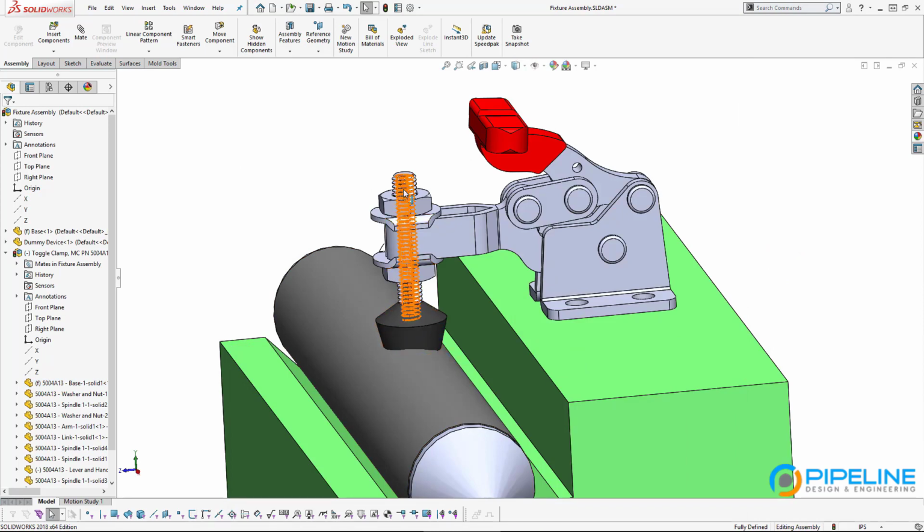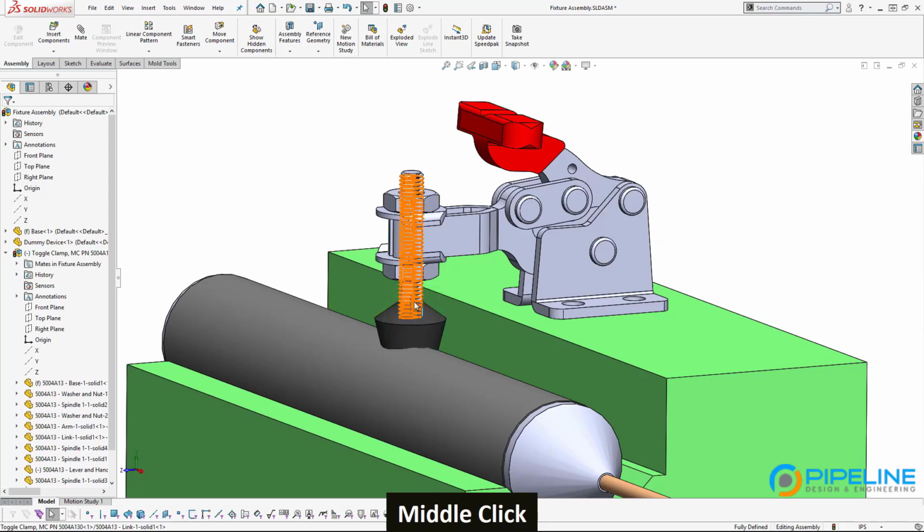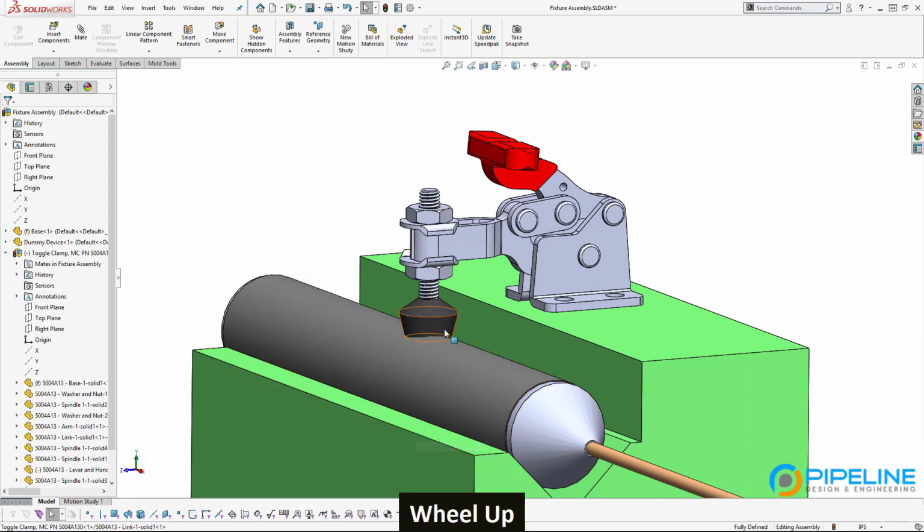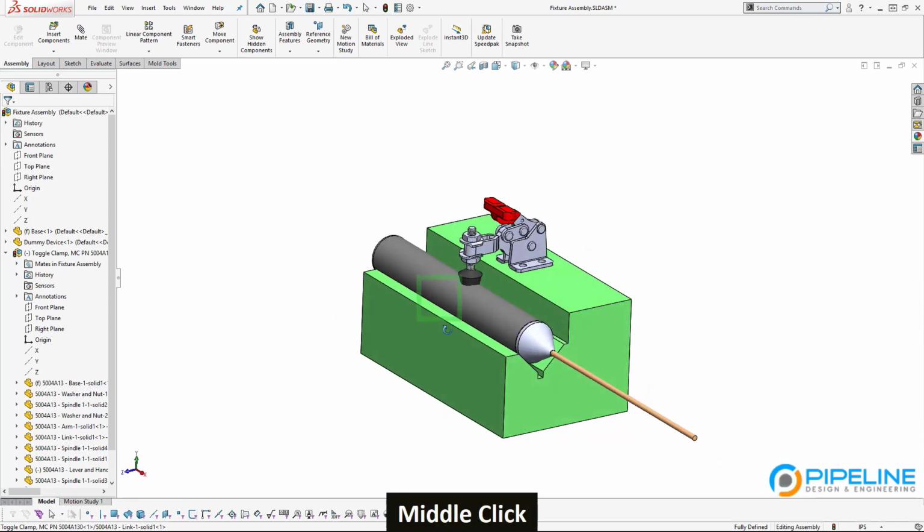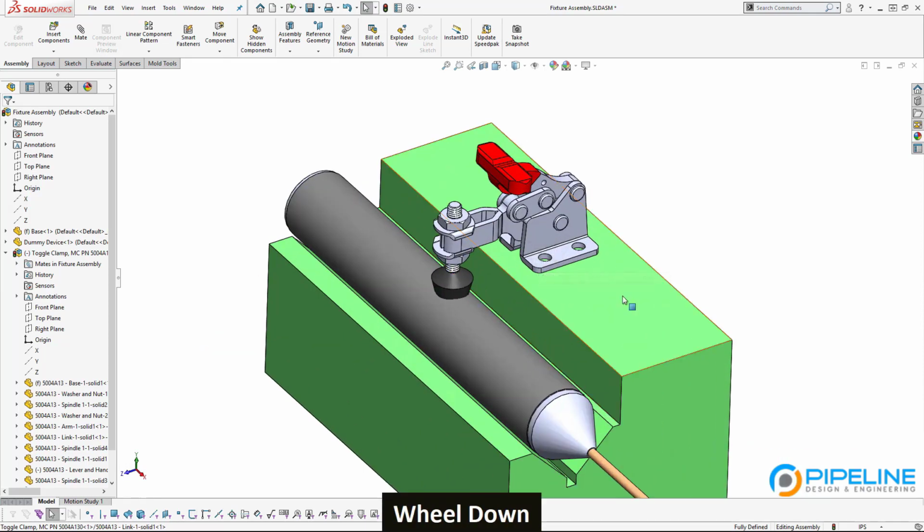But we also can see here that this toggle clamp is adjustable. If we needed that rubber stopper material to go up and have less interference with the device, then the user will be able to advance the screw through these nuts and have a little less compression here, which is great, that they can kind of dial in the amount of deflection that they want. So now we've got our first McMaster part dropped into an assembly, and we have to figure out how we're going to hold it down.